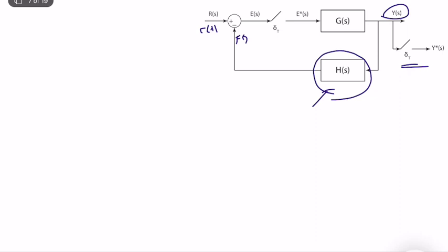After computing the error in the analog domain, we discretize the error signal, which is quite common in digital control systems. Instead of just discretizing the output, we take the difference between the reference and output and discretize it. This error signal E star of S, which is technically a discrete time signal, but we treat it as a continuous impulse train like signal, is filtered by a transfer function which looks continuous, but we know that it can have both continuous and zero order hold like transfer functions, to obtain Y of S. And the goal is, can we find Y of Z divided by R of Z?